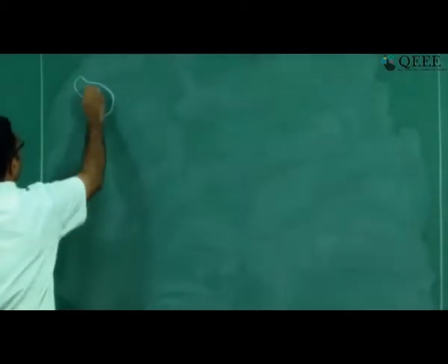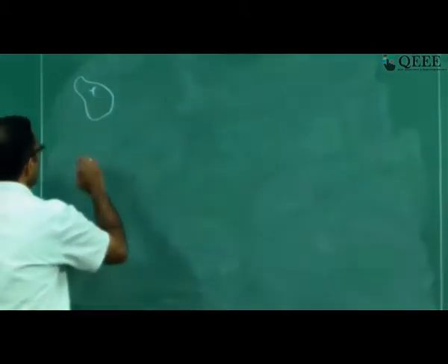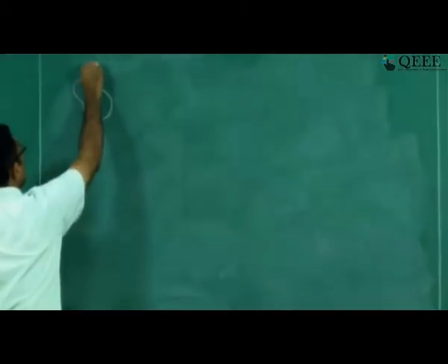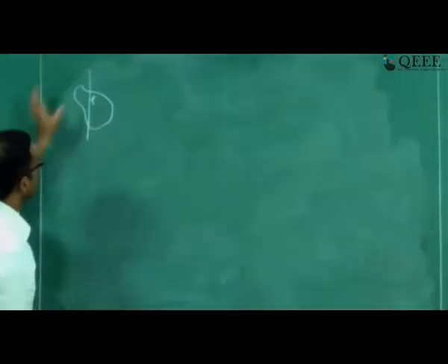So now let us take again an arbitrarily loaded member and take a particular point P. It's arbitrarily loaded, there are arbitrary stresses on the material. Now what we are going to do is pass a section through this P and isolate the left hand side off.